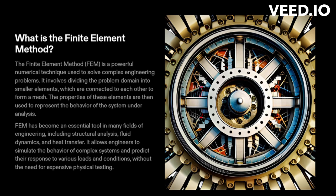What is the finite element method? The finite element method is a powerful numerical technique used to solve complex engineering problems. It involves dividing the problem domain into smaller elements which are connected to each other to form a mesh. The properties of these elements are then used to represent the behavior of the system under analysis. FEM has become an essential tool in many fields of engineering, including structural analysis, fluid dynamics, and heat transfer. It allows engineers to simulate the behavior of complex systems and predict their response to various loads and conditions without the need of expensive physical testing.